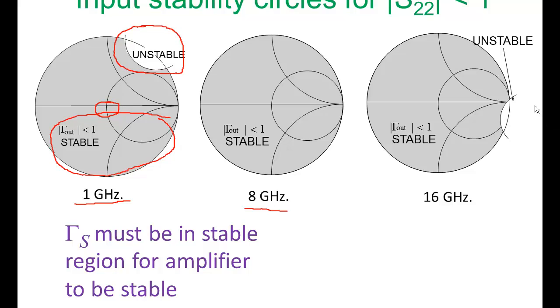device. Similarly here we see that we could go unstable at 16 GHz if we present something like an open circuit, or if we present, what would this be? This would be a capacitive element, very small capacitor that tends to look like an open circuit.